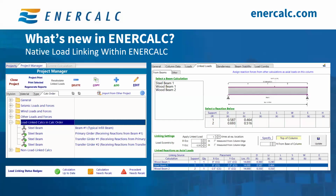If you're using ENERCALC in your daily workflows today for design of beams, columns, and general footings, you absolutely should be using load linking, which allows you to seamlessly connect your individual calculations to each other using reactions as applied loads in downstream calculations. Create durable dynamic relationships between your individual calculations, ripple changes down the load path, automatically associate those calculations without having to scribble, screenshot, or copy and paste those forces.